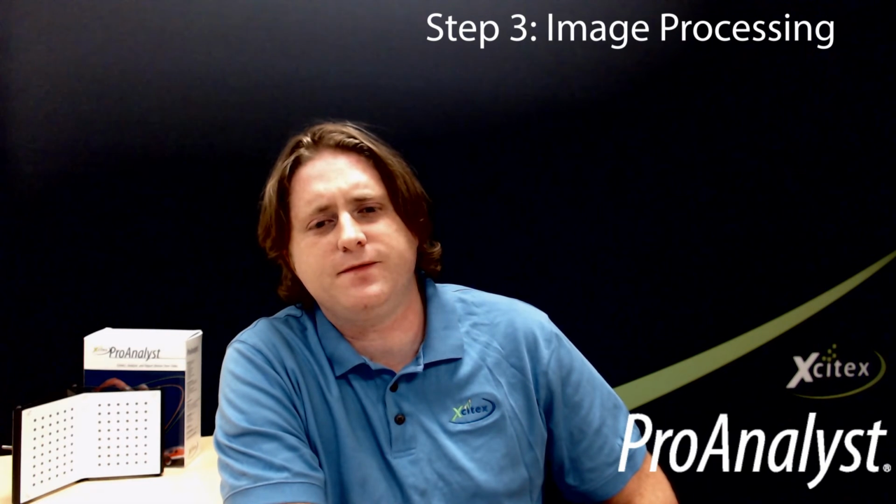Step 3, Image Processing. ProAnalyst has dozens of very complex analysis tools, all with very sensitive settings to adjust, and you have likely spent a long time capturing a beautiful, visually pleasing video. ProAnalyst doesn't care about that, and ultimately the easiest and most accurate analysis comes from ugly, high-contrast shots.